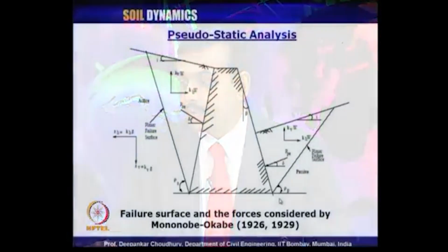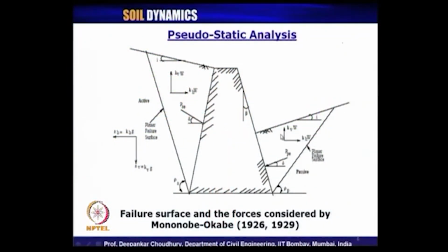And then in the case of seismic forces, additional two forces similar to this come in with four different combinations. So, these two seismic inertia forces will come into the picture, and among those again we have to do two optimizations, one with respect to this failure angle, another with respect to the direction of the combinations of the seismic forces acting on this failure zone.